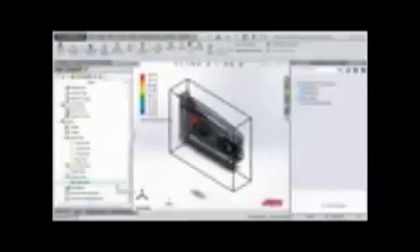Let's right-click on the surface plot and select Show Annotation for Plot Maximum. You can see that the high temperature decreased to 105 degrees Celsius, approximately 74 degrees Celsius less than the last simulation, and well below the upper limit for junction temperature of semiconductor devices, usually on the order of 150 degrees Celsius.